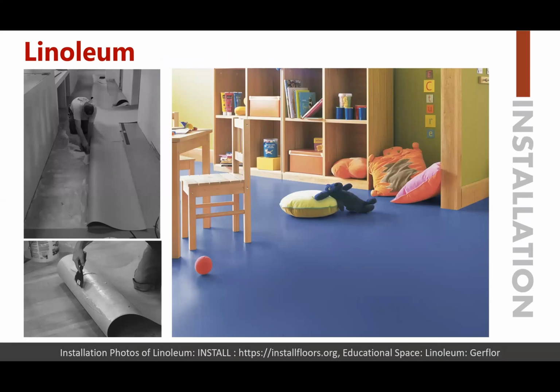Linoleum installation does in some cases require more knowledge and advanced skills in installation. The material has a propensity to expand in the width and shrink in the length when rehydrated in adhesive. There are techniques that mitigate that movement. There is also the possibility of end curl memory. Due to drying the material and rolling it in its packaging, the ends of each cut must be worked out prior to installation so as to, quote, break the memory and allow the material to lie flat. So when we go back to our conversation about installation and qualifying our subcontractors, this would be something you'd want to verify that they had familiarity with to make sure your linoleum installation is done accurately and successfully.